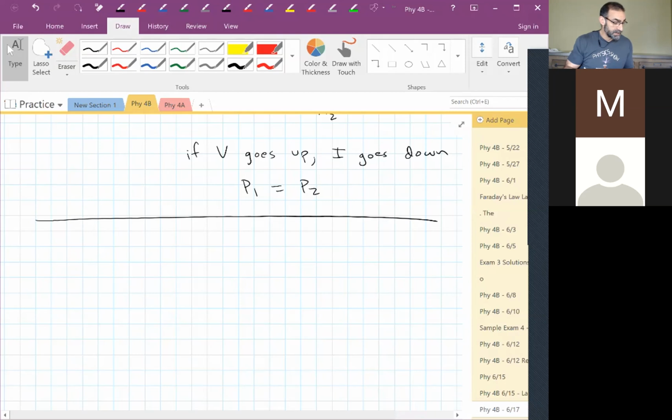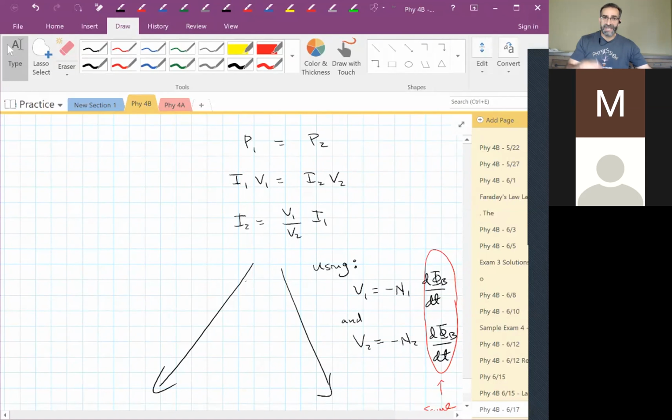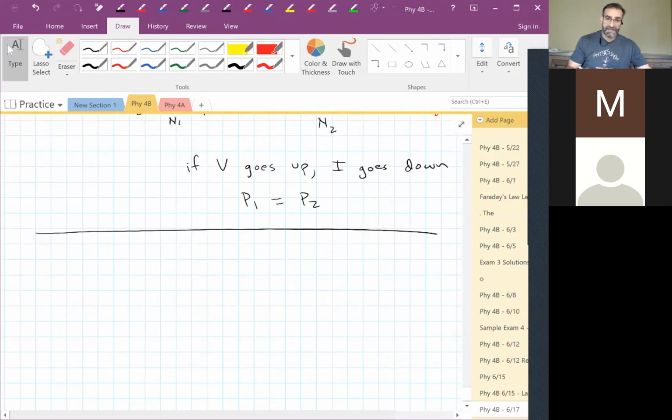So let's talk about that. First thing we need to do is convert. We already know how to change the voltage, right? We use a transformer. Transformer can change the voltage down. Now we have to change that AC low voltage signal into DC so we can plug it into our laptop, right? We use a rectifier.